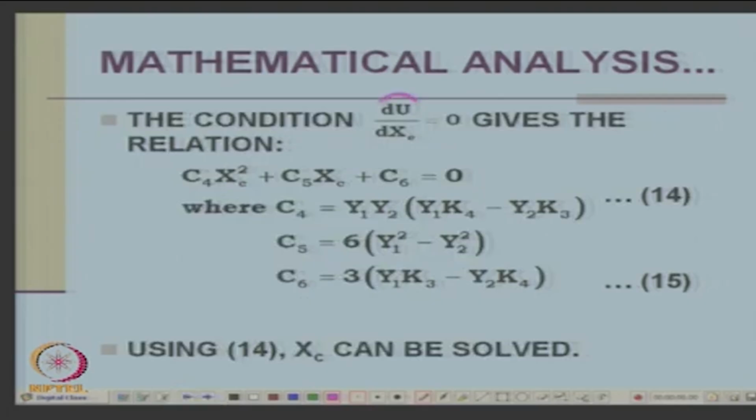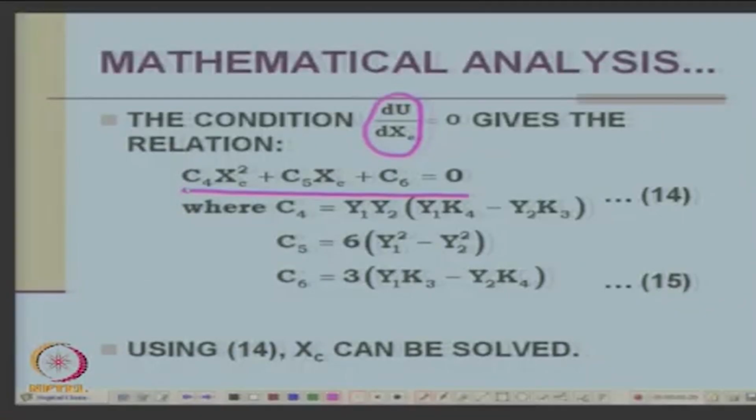So, you have to find out the capacitance to give minimum unbalance at a given speed. Is it similar even on star connection, is it okay? At a given speed you have a motor with a capacitor running, and you do not want it to have too much negative sequence. So, you get another quadratic equation, okay.